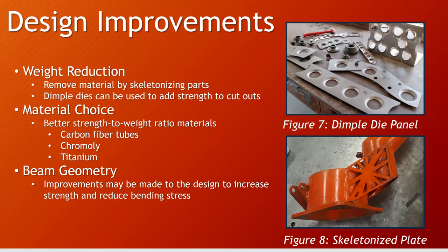The factor of safety of the beam is above 2, and 3 for the links. The worst point of failure was in the tabs themselves. By increasing the tab thickness and reducing sizes of material and hardware elsewhere, we can ensure that the tabs will not fail while decreasing the weight in the rest of the beam.